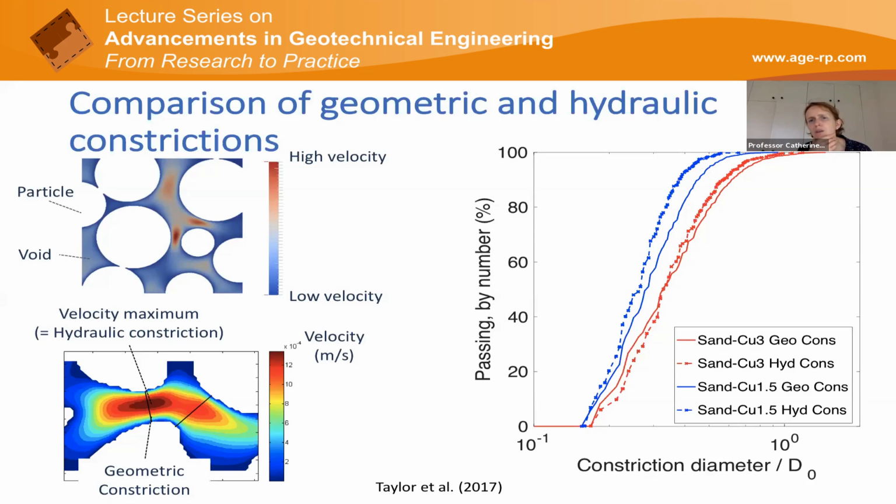Thanks, Catherine. This one comes from Benedicta from University of Edinburgh, and mentions that she had used resin to impregnate rammed earth before. Is it possible to explain in more detail how you impregnate the resin when the specimen is in the triaxial cell? Yeah, to impregnate rammed earth could be quite tricky because the permeability will be a lot lower.